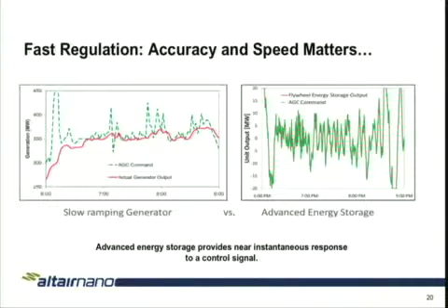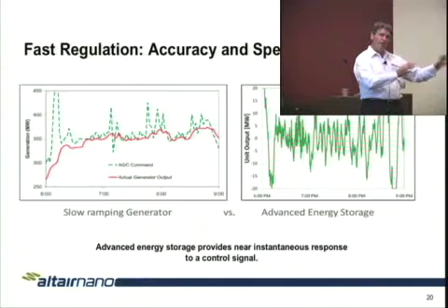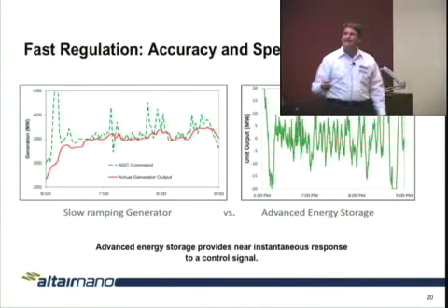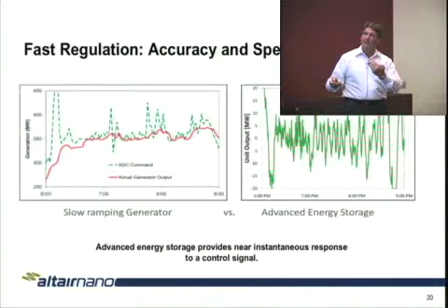And once again, this signal is being generated by the imbalance of power flow going from one balancing authority to another. As you look at the actual generator output, you can see that in order to match this, they're going to have to schedule for more capacity than just this amount. In order to get up to the top of this, I'm going to need maybe 5 times more generation.